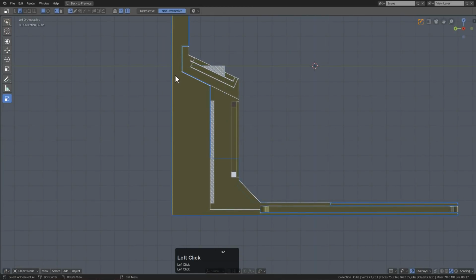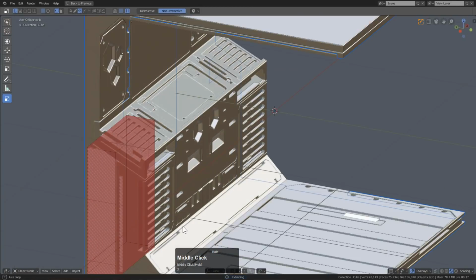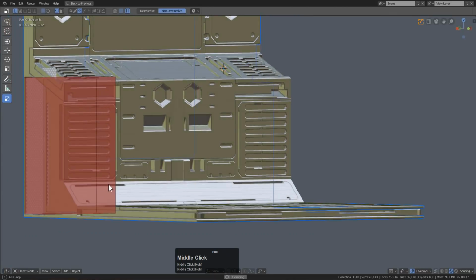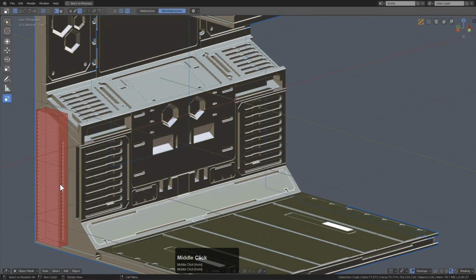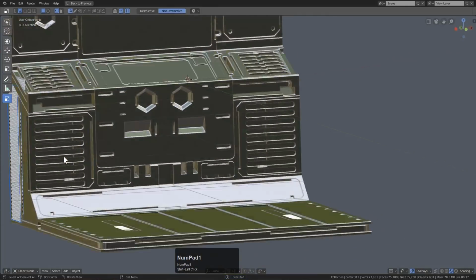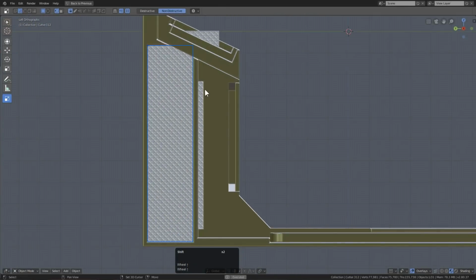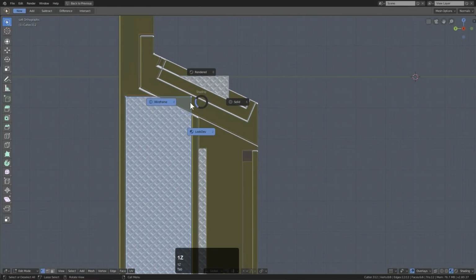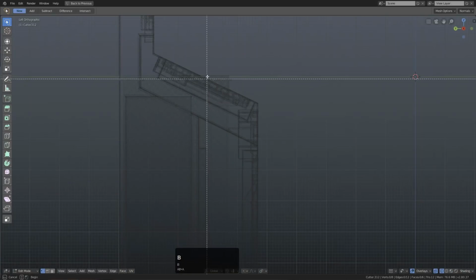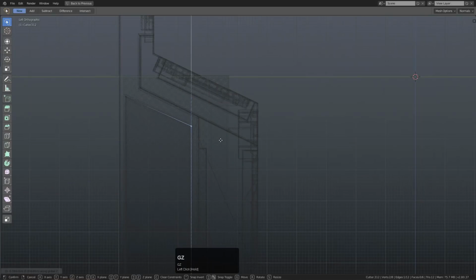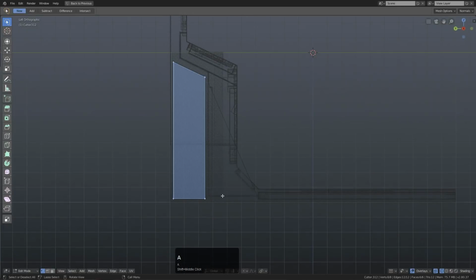So right here, I'm going to draw a red box. We're going to bring it in. I love drawing on the surface in a flattened view and then rotating the view and watching this thing get deep. It reminds me of Fusion 360. So right here, I'm going to hold Shift. We're going to keep this. We're going to look at this from this side, and we'll just go into wireframe. Been trying to bring wireframe back into my life. Wireframe was a dear friend to me.